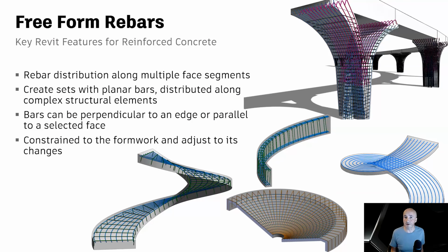In addition to shape-driven intelligent rebars, Revit offers you freeform rebars. You can use the freeform rebar tool to model bars in any concrete host, regardless of its complexity, mostly for civil structures, but also for regular building elements where you need a set of bars following a curve or something similar. This type of reinforcement differs from shape-driven rebar by the fact that the bars get their geometry exclusively from the geometry of the host. We call this type of reinforcement host-driven.